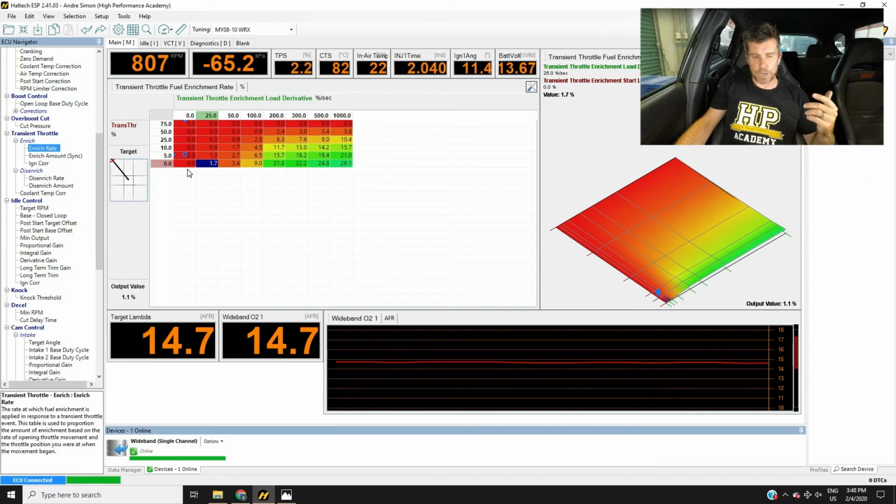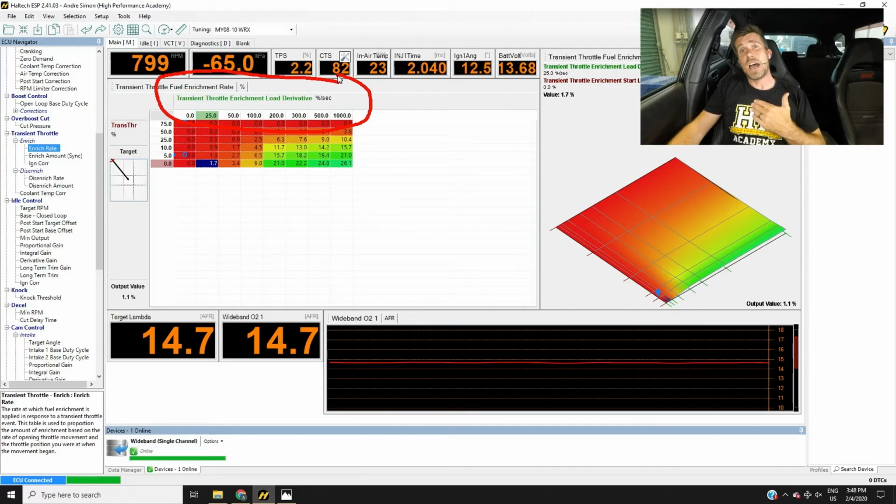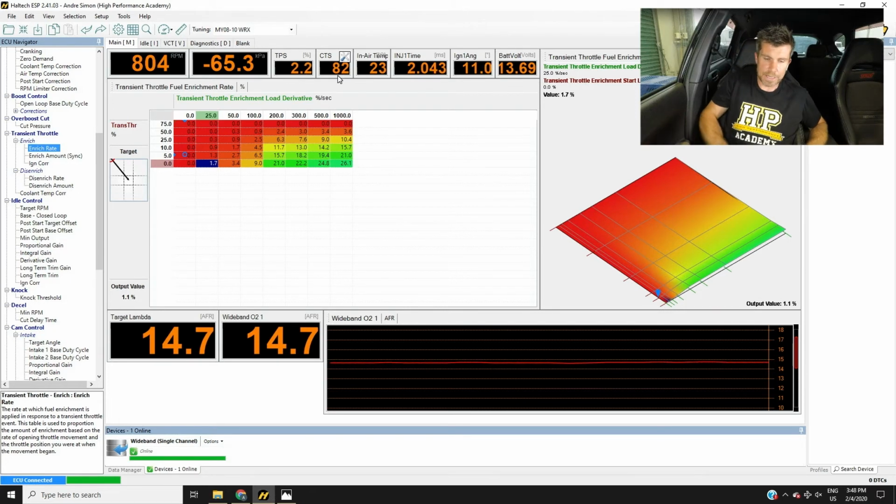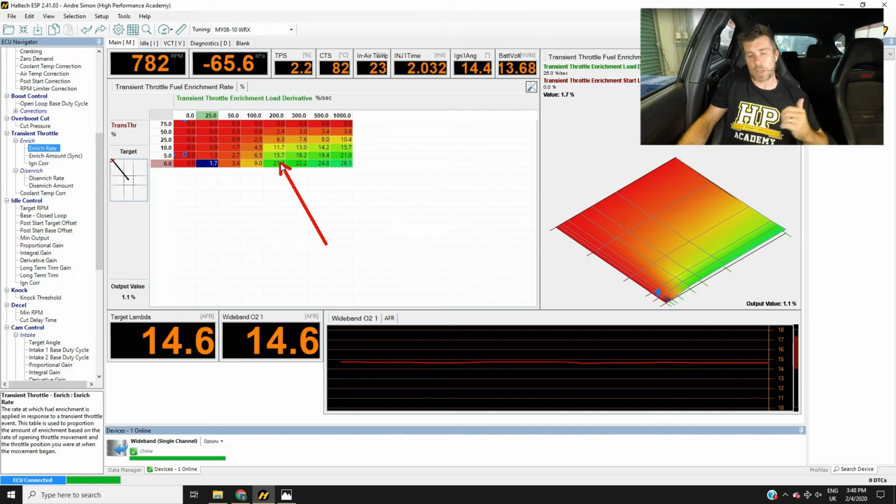of the way. So the other axis here, this is the rate of change of throttle. So again, the more quickly and more aggressively we open the throttle, the more fueling we're instantaneously going to need. So again, if I just smash the throttle open, hopefully what you're going to be able to see is that that little blue circle is going to move out here to, I think, depending on how quickly I do it, around about 200%. So let's just try that. Okay, it did exactly that.